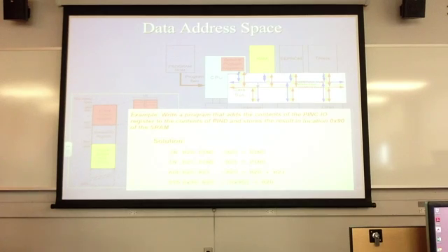Now, if I want to write a program that adds the contents of PINC, the port C register, to the contents of PIND and stores the result in memory location 090, here all I do is read in PINC, which gives me the contents of port C. It gets loaded into R20. D gets loaded into R21, add them, and then store them.